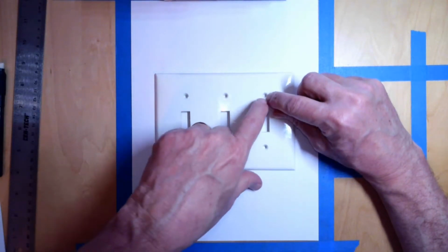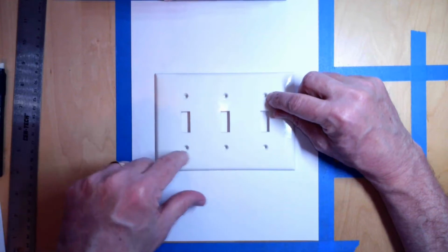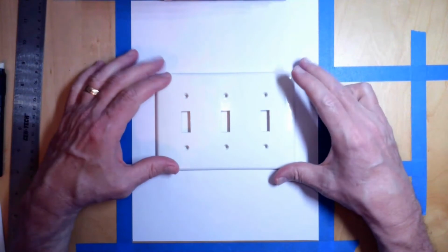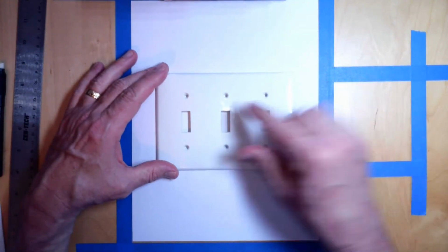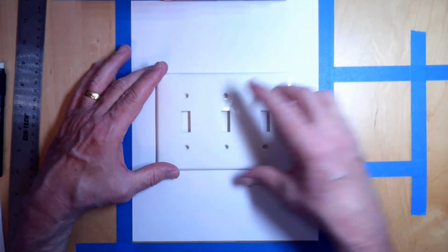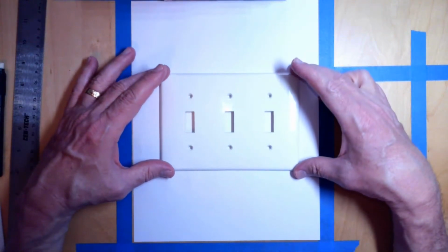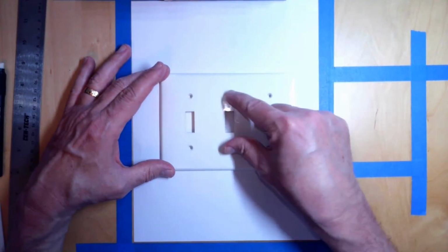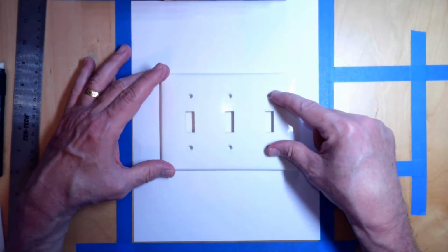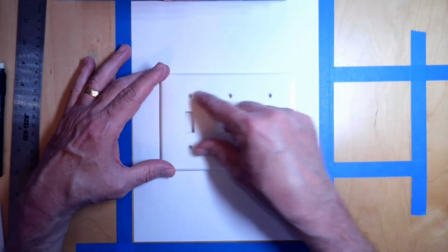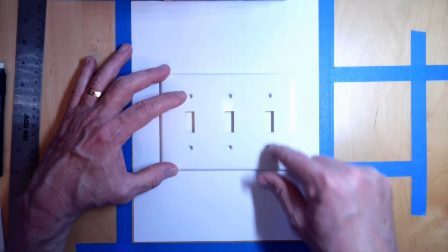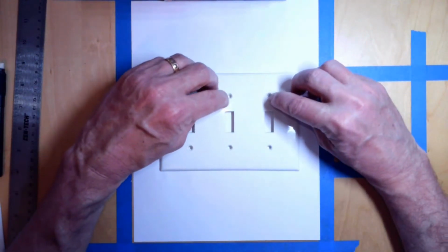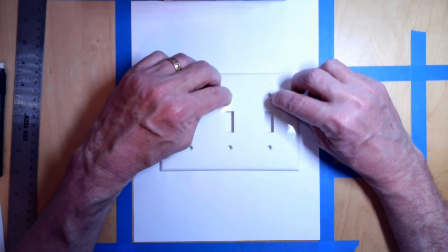So the tolerance zone for the screw holes here needs to be pretty tight. Okay. So if I was going to make a drawing of this outlet cover and assign a positional tolerance to these holes, I would need to make sure that the tolerance zone for these holes is relatively small, because I can't have a lot of deviation here.